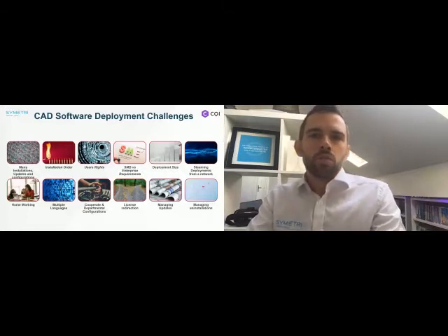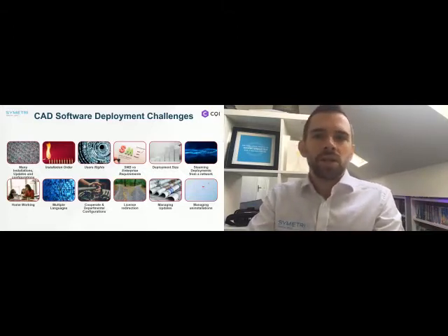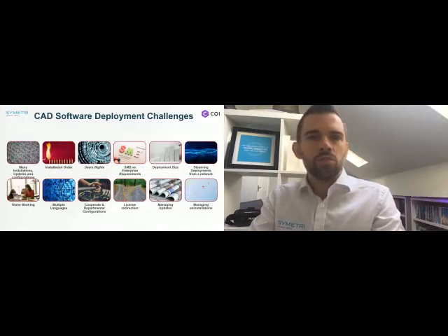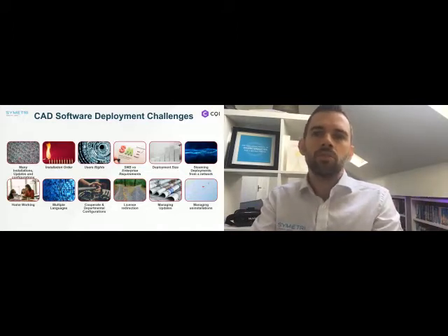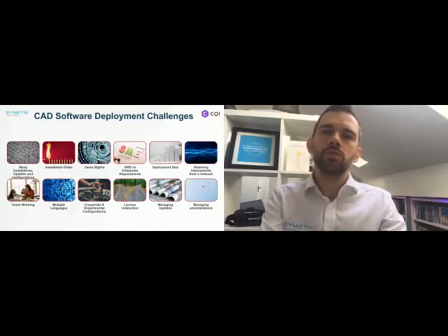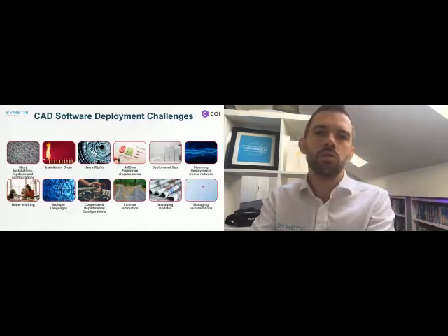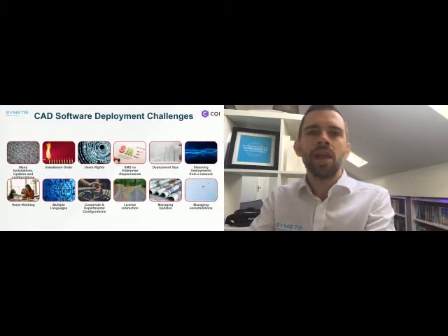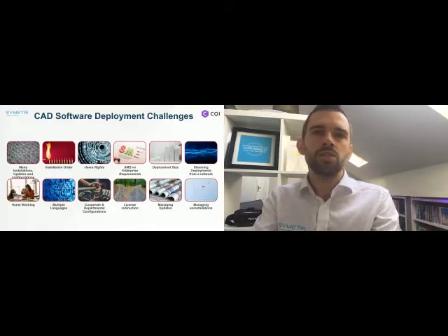The order that we install the software packages does make a difference, less so in 22 release than it did in 21. If you look at the mechanical design packages, if you install AutoCAD and Inventor, you historically would have to put those on before you put Vault on, otherwise you wouldn't have the right access into your data management system. Now Autodesk have started to allow you to install in different orders, but still the installation order matters.